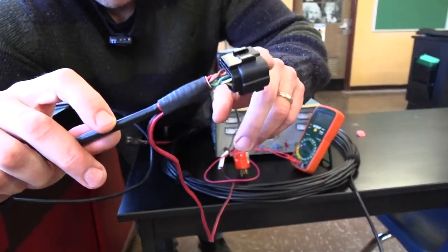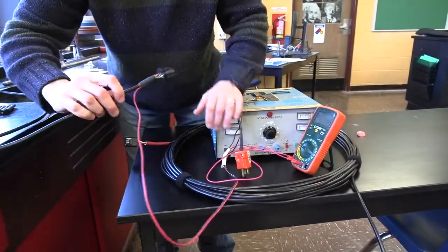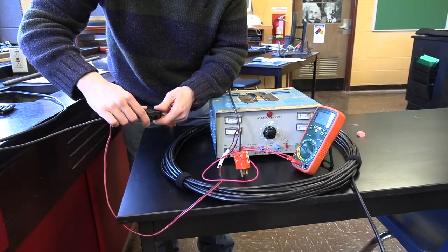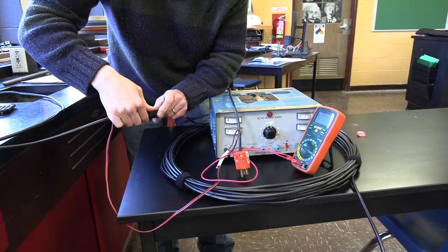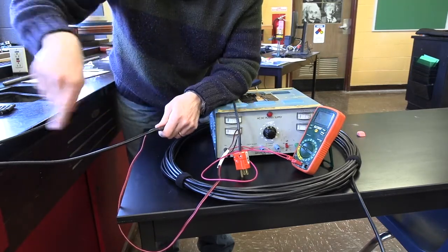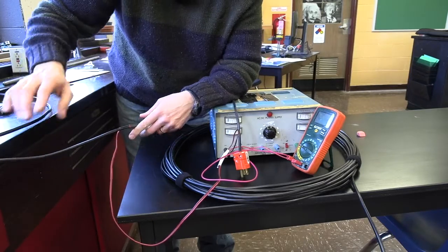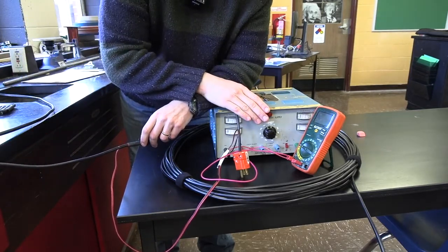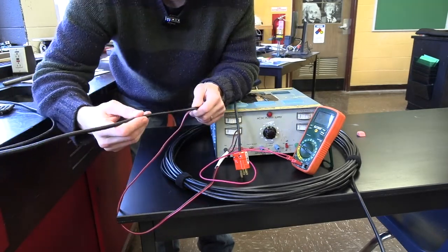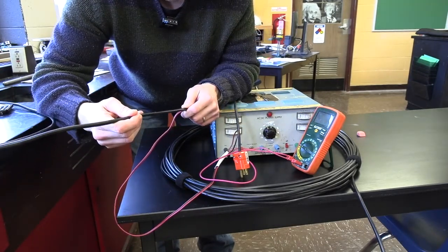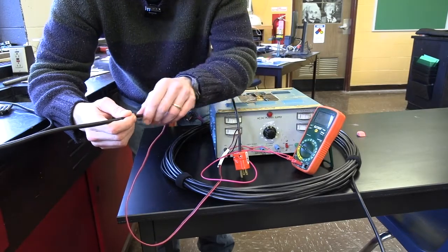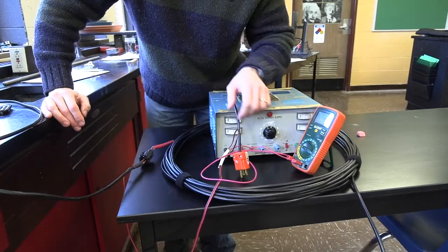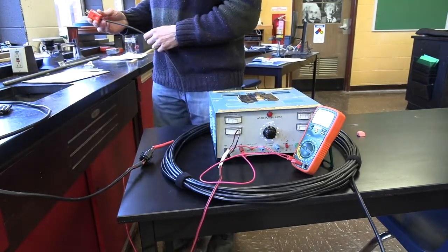I put a connector on here so that when I connect it to this end of the wire, it makes the current spiral and go 7 times around the wire loop that I've established around the room. So any current that comes out of here is going to produce a net effect of 7 times the current going through each individual strand of the wire. A clever way to boost up the amperage.